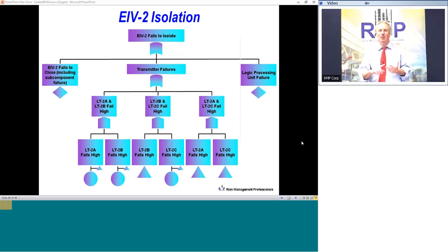And this transmitter reliability is dependent on the manufacturer, the system configuration, how often it's maintained and calibrated, and also what environment it has. You know, how good a transmitter is it? Is it in dirty service? Is it in clean service? So all those things need to go into your consideration of what's the contribution of transmitter failures to the overall unavailability of the function. And that's what you need to consider, these concepts, when making decisions on how much voting logic or sensor reliability you need.